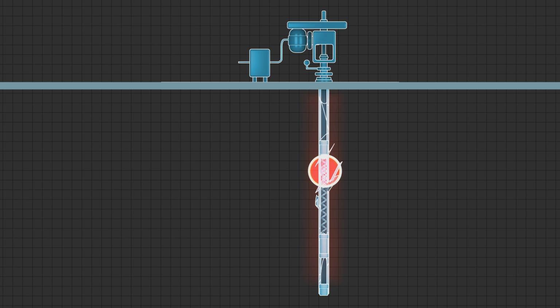In other words, they'd lose 8 hours of production for an event that lasted 1/10 of a second during a recloser. So we considered mechanical solutions involving stopping the backspin of the shaft, but the risk of damaging or breaking the shaft was significant, and the cost of pulling the damaged shaft was on the order of $1 million. So what did you do?